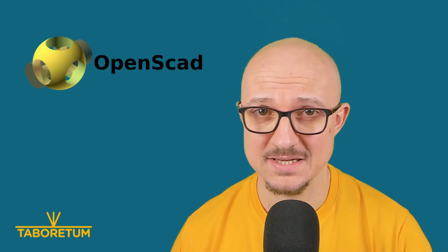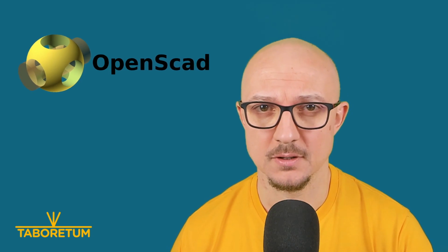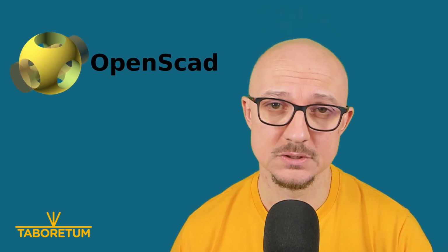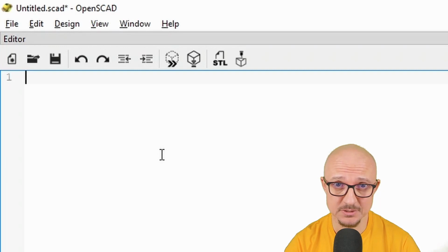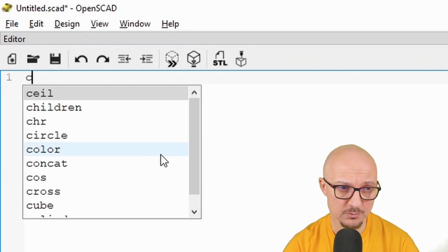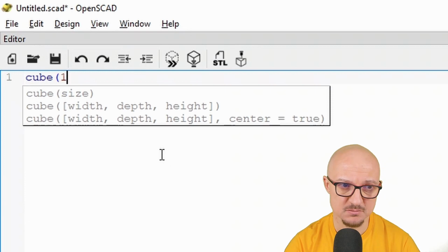We'll start with OpenSCAD. This is a program that I learned as a first CAD software. It is a bit strange because you write code to describe the object you are modeling, the shapes. And of course it has advantages and disadvantages, as you can imagine. I've measured that the dice is roughly 16 millimeters wide. So we start with a cube. It will be 16 millimeters.